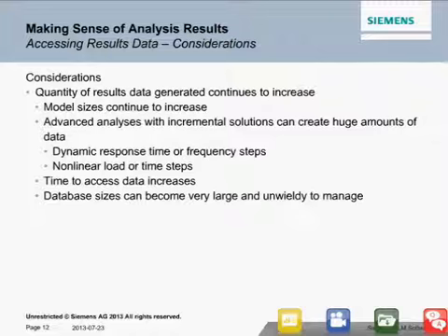Also seeing, people are moving beyond just performing linear static analyses. They're getting into dynamic analyses and dynamic response analyses, in which the data is calculated on a step-by-step basis. If it's a frequency response, it's by frequency, and a transient response is by time steps. So there's a lot more data that's being produced in post-processing. Similar for nonlinear approach as well. That tends to be load incremental. So again, data is produced at increments.